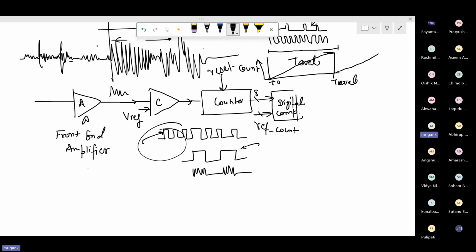So if the frequency of the seizure is, suppose, up to 100 kilohertz, then even within a few milliseconds you can detect. Within 100 milliseconds at max, you can easily detect this onset. So time domain detection can happen pretty fast. The target is to detect it as fast as possible, so that it does not lead to a full-blown seizure and the person goes into convulsion. For that condition, we need to detect it as early as possible.